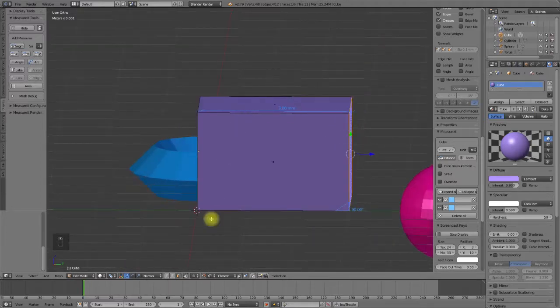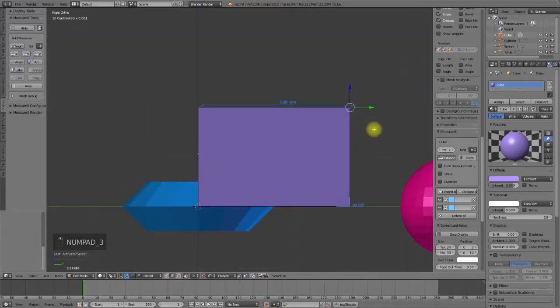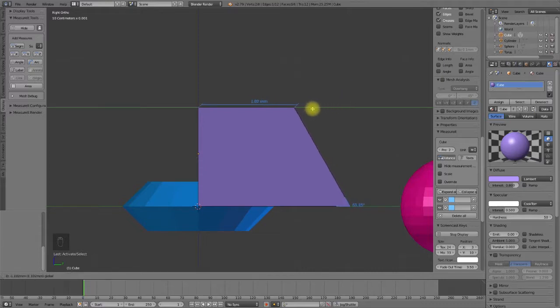I want to preserve the overall height, so I select now the edge. Make sure we have the correct direction activated. So I change this to, let's say, global, and now I can move this edge on the y-axis until I have 45 degrees. Use the shift key to make smaller steps in combination with the mouse, and now I can set exactly the angle to 45 degrees.